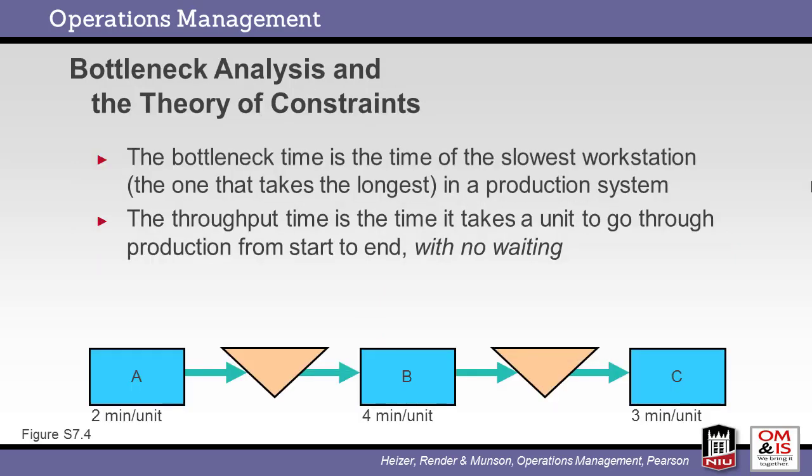A bottleneck is that part of the process that is the slowest or has the lowest capacity. Think of a garden hose with a kink in it. The flow of water can be no greater than that through the smallest hose cross-section. The goal of bottleneck analysis is to analyze the process from beginning to end to find the bottleneck process. Effort would then be taken to address the bottleneck by improving its capacity and throughput. Note the difference between cycle time and process time.